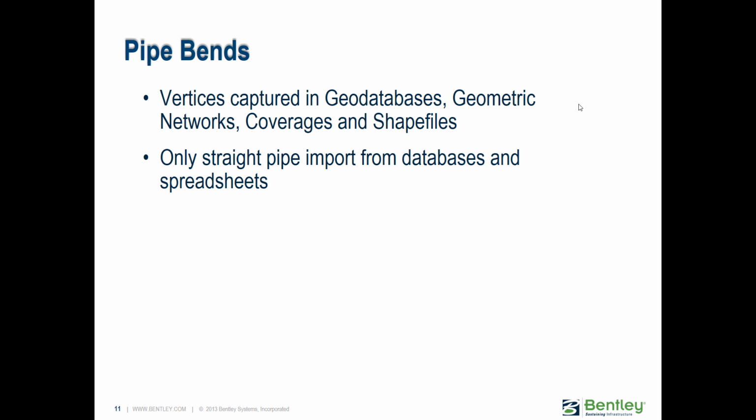A note on pipe bends. So I touched on this a little bit, but files like spreadsheets or databases, they don't really contain the bend data. You just have a start node and a stop node, so you just get a straight line. So if you're looking for more detailed information that includes bends of your pipes, you'll want to be working with geospatial information.